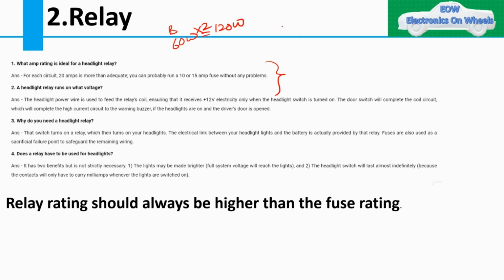If I cross-multiply it, V equals IR, and we have our I around 10 amps. For 10 amps, in the last class I have shown you the fuse value. If I take 1.25 as the multiplication factor for the fuse selection, it will come around 12.5.